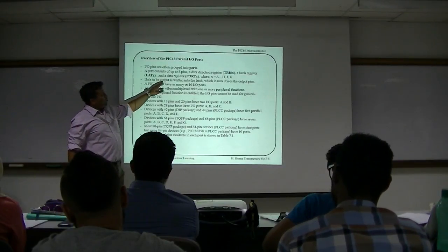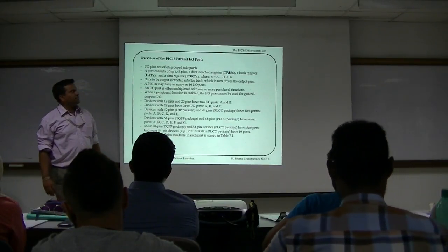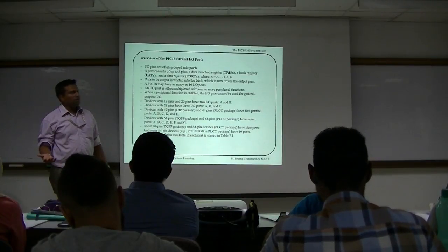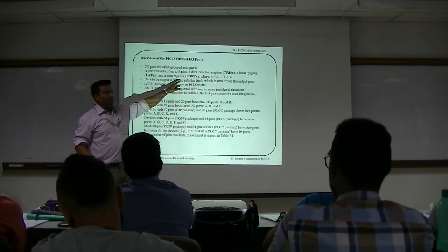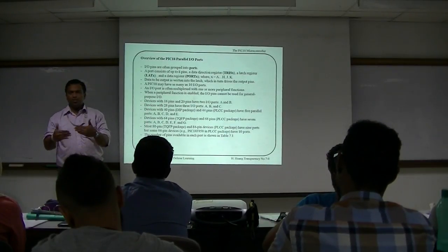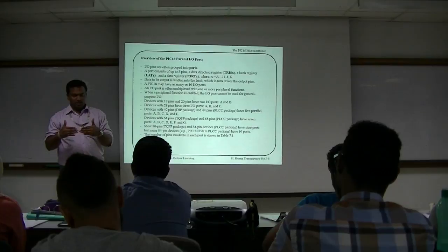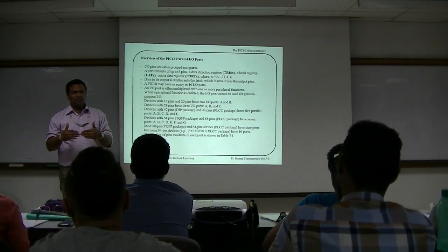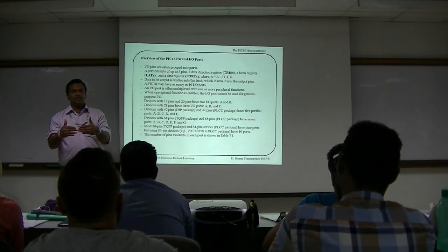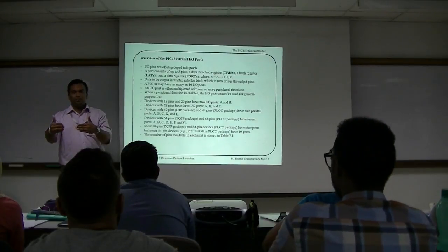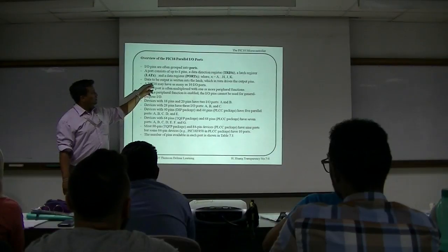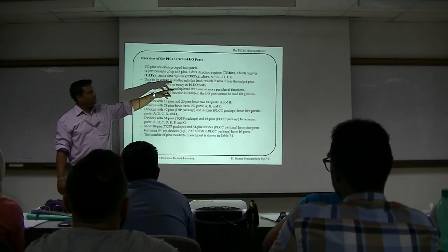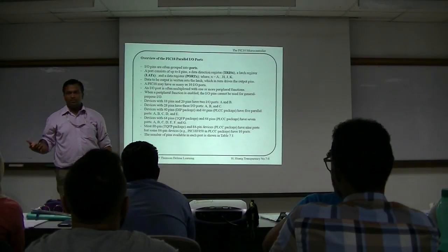So the data to be output is written into the latch, which in turn drives the output pin. So whatever we are dealing with, we always deal with the port. Whenever we send the data to the port, we will actually send the same data to the latch register. The latch register is actually connected to the pin circuitry. So that's why it says that the latch drives the output pin.